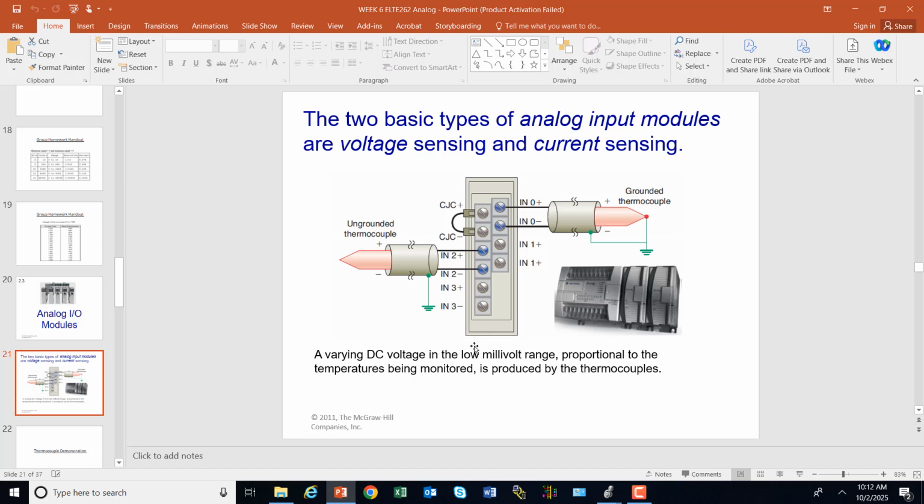There's a little dial that we can use to dial up the voltage, 0 to 10 volts, and that's what we're going to be reading. As we move on next week, we're going to be current sensing, and we'll be using a temperature transmitter, and then we'll be using a thermocouple module. Okay.